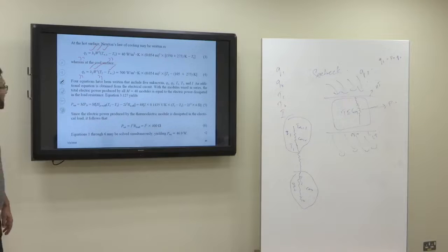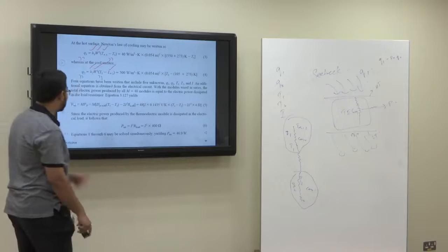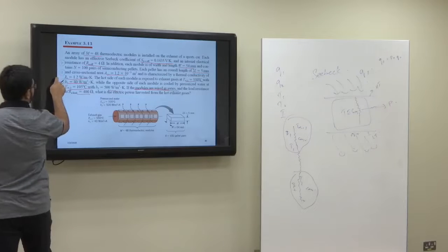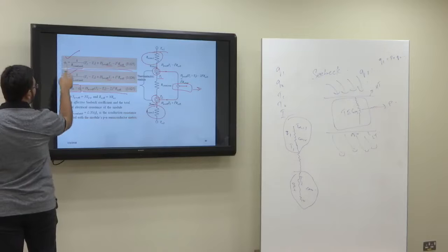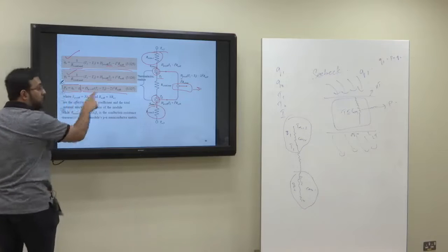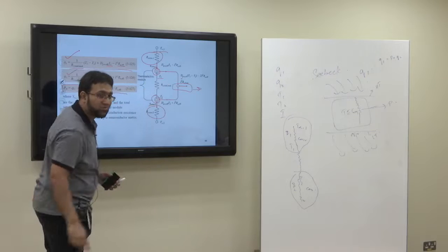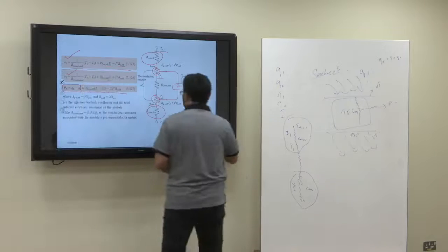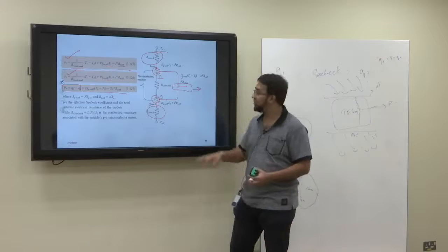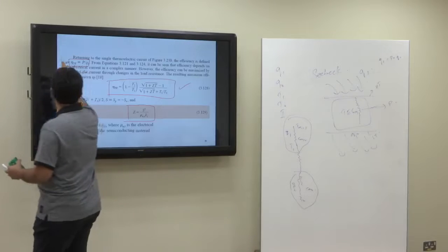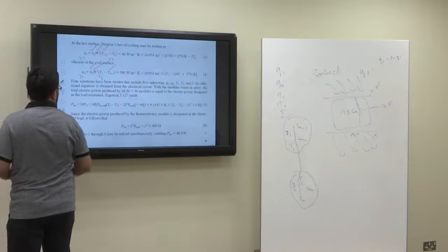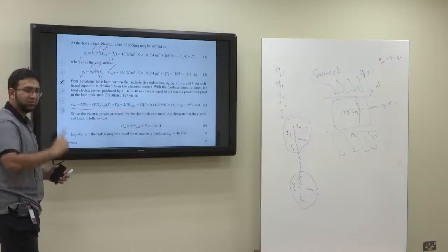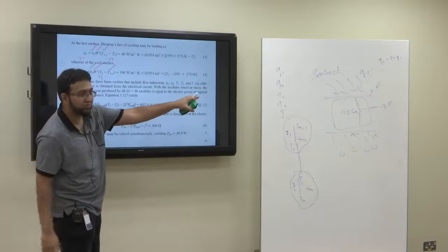Now what you can do is put in another equation, the one for the total. You remember we had the equation with Q1 and Q2, based on the first law of thermodynamics: Q1 equals P plus Q2, so P equals Q1 minus Q2. This is for a single module. Because there are 48 modules, we put the same equation here but multiplied by m, because this is going to produce the total power output.